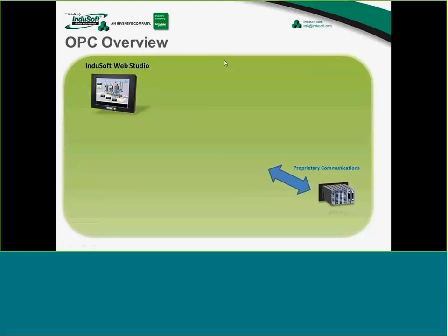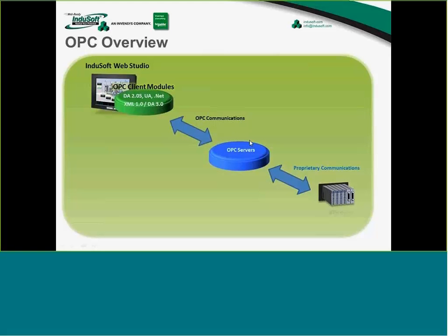then be able to use something like an OPC server. Now, when I talk about an OPC server, that's a piece of software. That's not a physical, like rack-mounted computer. No, that's a piece of software. And in this case, InduSoft Web Studio would be the client. Now, we, again, have support for OPC DA, UA, .NET, and XML as clients. What we're talking about in this webinar really is UA.